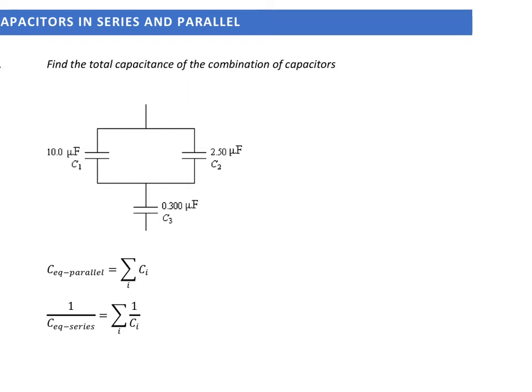There are capacitor circuits where series and parallel result in one kind of pattern. And there are resistive circuits, things we'll study after spring break, and the pattern is flipped. So when you get one kind of effect with capacitors in series, you get the opposite effect with resistors in series. Same thing for putting these things in parallel, resistors or capacitors.